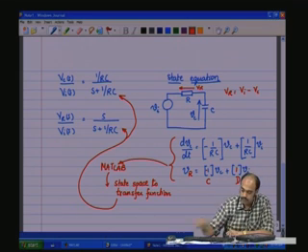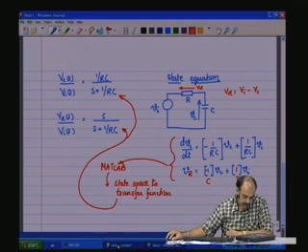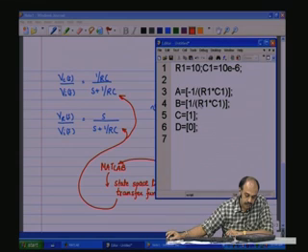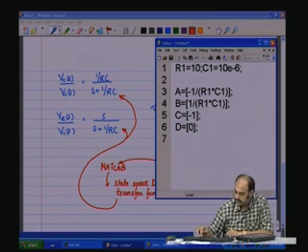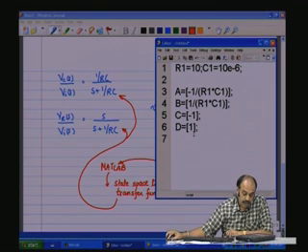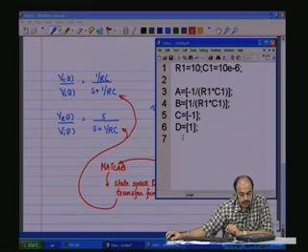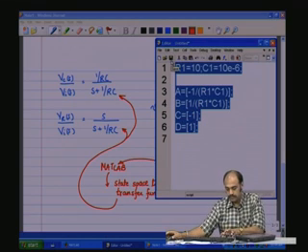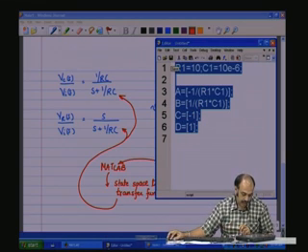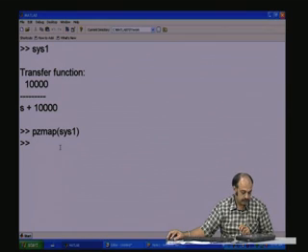So, let us do that modification in the MATLAB editor. So, we make C as minus 1 and D as plus 1. So, now with this state equation, this represents VR as the output, which means we can now obtain the transfer function.